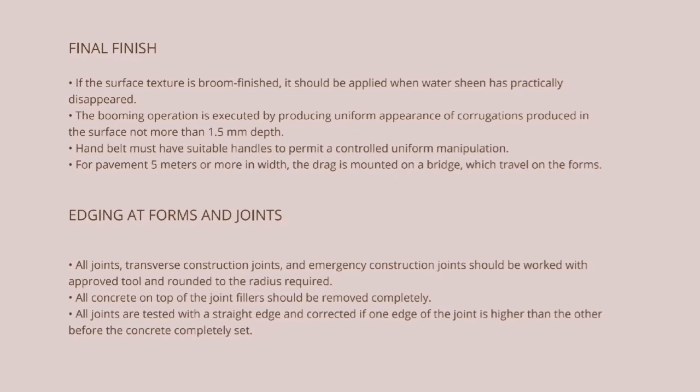Edging of forms and joints. All joints, transverse construction joints, and emergency construction joints should be worked with approved tools and rounded to the radius required. All concrete on top of the joint fillers should be removed completely. All joints are tested with a straight edge and corrected if one edge of the joint is higher than the other before the concrete completely sets.